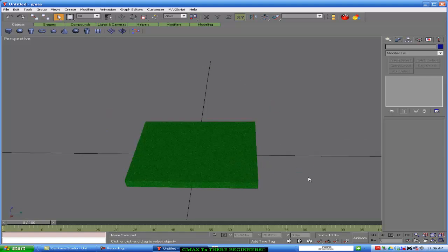Okay. Got the deck pretty much made. We've got it at 40 by 40, 4 meters by 4 meters. We've got it textured. It all looks pretty good there. What we want to do now is make 2 more copies of this deck. Why? Well, because they want 3 different distances of view. Now, if this was a complicated model, you'd want the LOD 2 is the worst. You've got LOD 0, that's up close. LOD 1 is a little distance away, and LOD 2 could be up to 300 or 400 meters away.